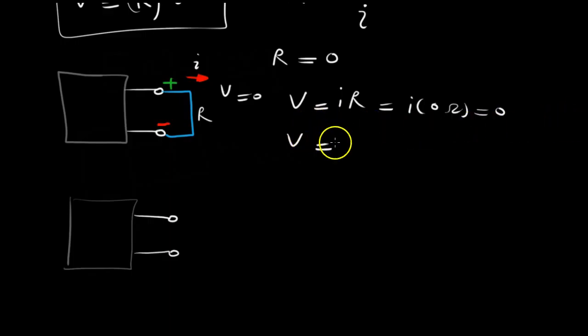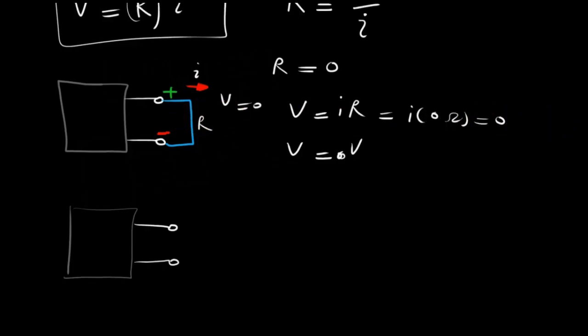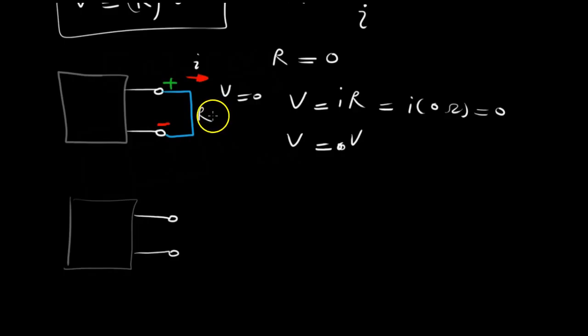So that's one thing to remember. And you always want to watch out for short circuits, because you can have high currents flowing through a wire, and you can heat up that wire, and you could damage components. So you always want to make sure you don't get short circuits. The only reason we use short circuits is in theory, where we assume that wires have 0 resistance, and we simply do it for simplifying the math.